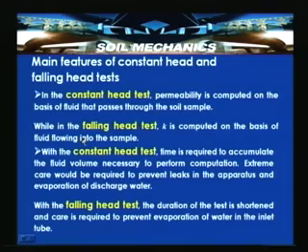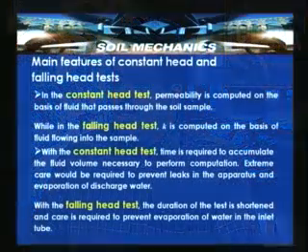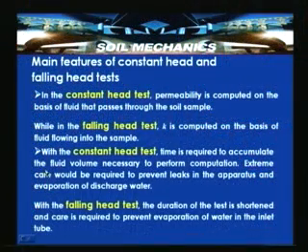With the constant head test, time is required to accumulate the fluid volume necessary to perform the computation. Extreme care is required to prevent leaks in the apparatus and evaporation of discharged water.